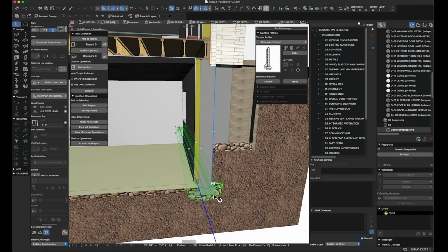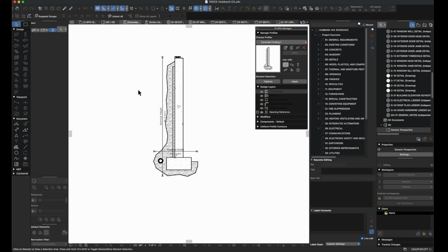You would even want to go a step further. I would even separate out the footing from the foundation drain, the chimney, and all that as yet a separate complex profile. But what you can do is when you go into that complex profile editor, you can actually draw it up like you would do in a typical 2D section. But then you can duplicate these using the duplicate command for the profile manager, and then delete out the parts of the complex profile that you do not want. It's a great tool, and this is not the only area where you can use this tool. I've used complex profiles for 3D details, and I do have to give my props out to Tim Ball out of the UK. He is the one that I learned this from through Eric Bobro's master classes, so credit goes to him.